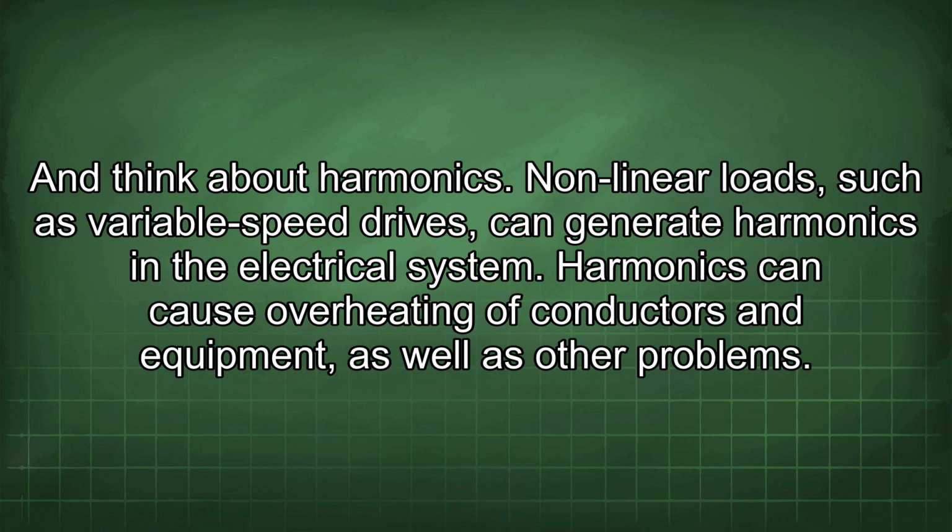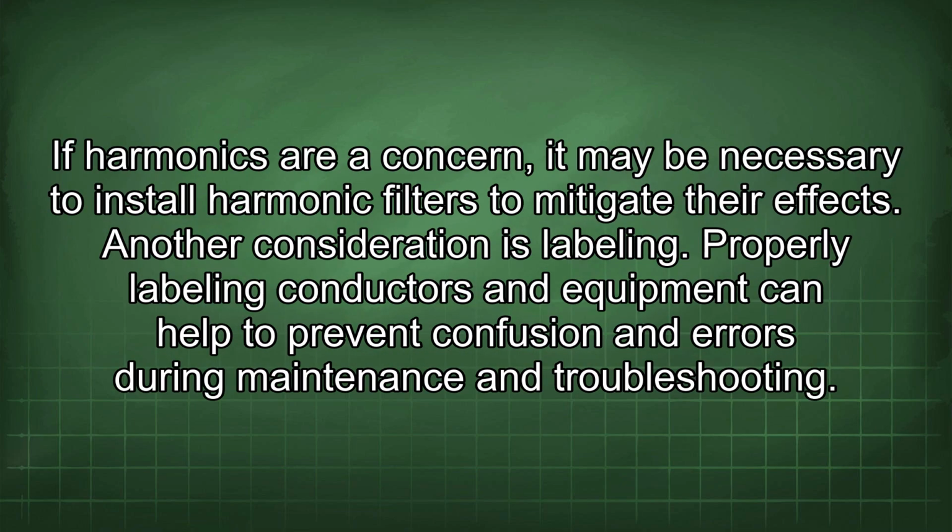And think about harmonics. Nonlinear loads, such as variable speed drives, can generate harmonics in the electrical system. Harmonics can cause overheating of conductors and equipment, as well as other problems. If harmonics are a concern, it may be necessary to install harmonic filters to mitigate their effects.